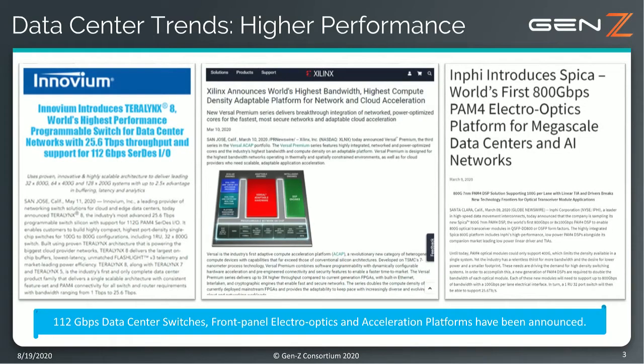When we look into data center, at least again from Samtec's perspective as a component supplier to data center equipment manufacturers, one of the things that we're seeing is the ever-increasing need for speed. Right now, current generation products available for data center equipment typically feature 56G PAM4 channel data rates. Silicon solutions at those data rates are commercially available as we speak. But in recent months, we've started to see several leading semiconductor companies start to announce their roadmap products for 112G PAM4 solutions.